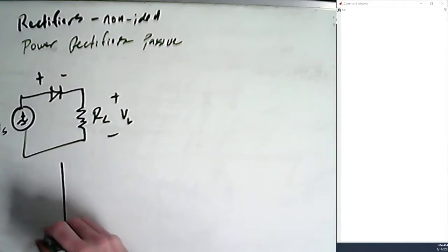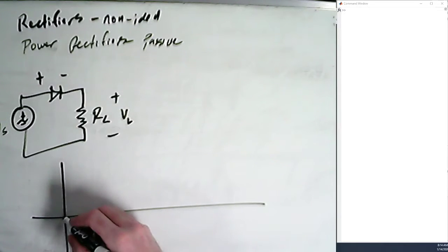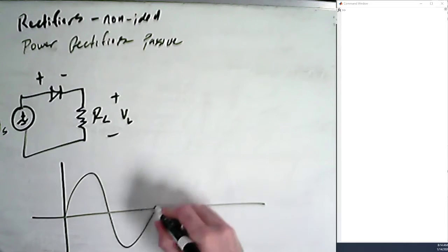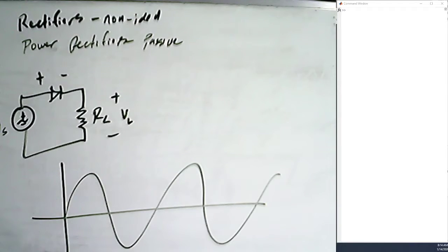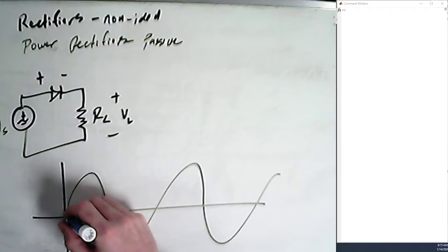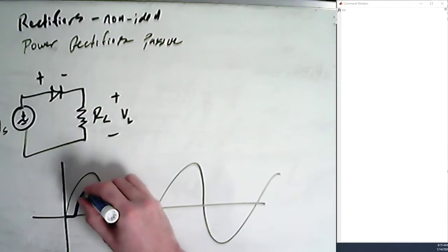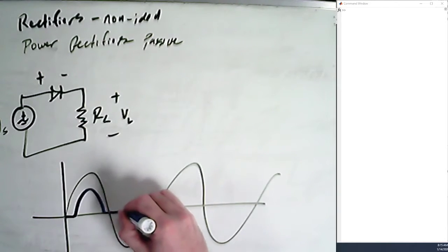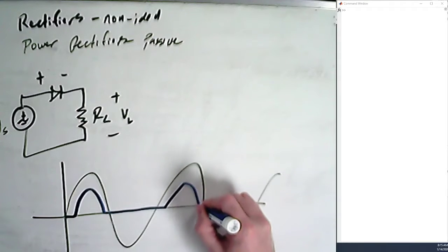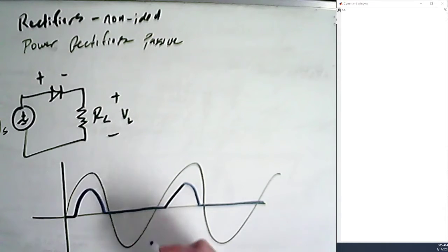And so when we plot this, and we plot VS, if it were a perfect diode, we'd expect there to be a match, but there's not going to be, because we had a 0.7 volt forward bias voltage drop across that diode. We get zero the other way. And so this ends up coming in here. Okay? And it looks something about like that. This shouldn't surprise you too much. We've talked about this already.